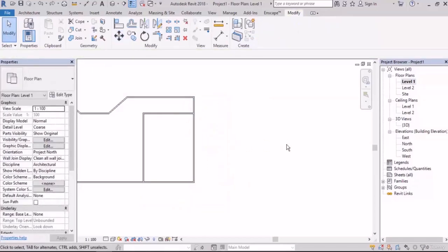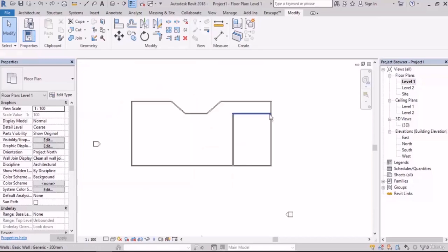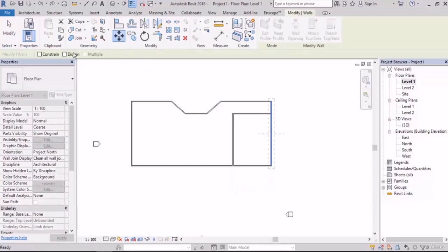Alright, I want to tell you something and I want you to keep it in your mind all the time. If you move an object and we see that another object is being moved with it, remember that you forgot to activate the disjoin because you wanted to move only that object. This thing happens many times without you understanding. For example, you move the console upstairs and it moves the wall downstairs too.